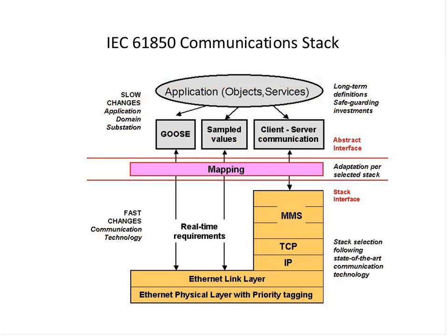And GOOSE, as you can see, runs straight on Ethernet, which allows that 4 millisecond response time for protection within a substation. So you see how these services are being used to support different things. Key thing to understand here: the full stack, the TCP/IP stack, can support IEC 61850 commands going across, let's say, a wide area network, as you can see in this example.